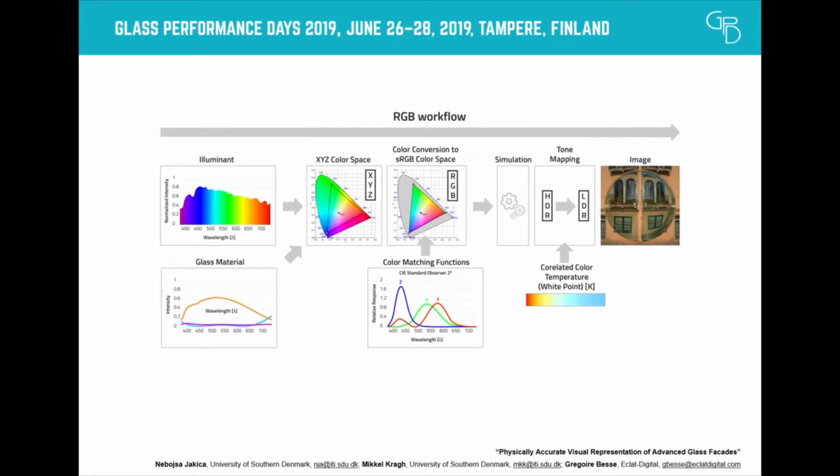So take a look here at the simulation that comes after the clipping. You basically lose the information that you sometimes need with complex scenarios, especially when you have some peaks in the source illuminant, if you have mixed lighting, if you have goniochromatic coatings that can change color depending on the angle.